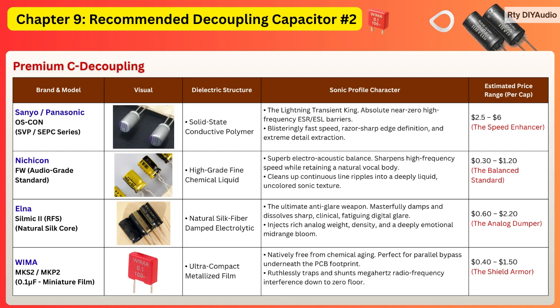Let's execute our final curtain call for the Capacitor Masterclass with Chapter 9, Recommended Decoupling Capacitors, Part 2. Positioned directly at the core active semiconductor and integrated circuit power pins, these localized decoupling units function as your high-speed miniature transient reservoirs. To ruthlessly shunt megahertz radio frequency interference directly down to zero floor while avoiding parasitic ESL inflation, we